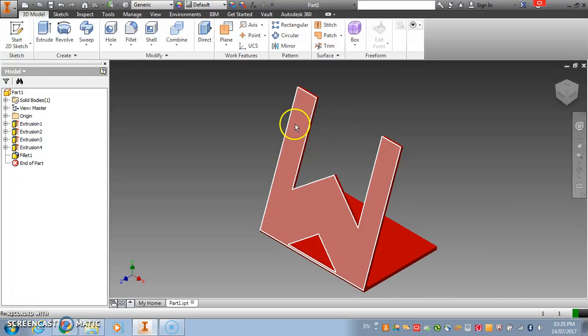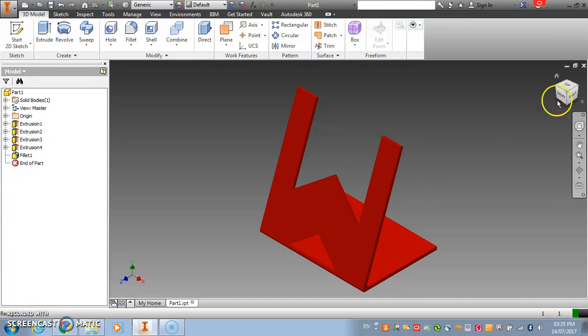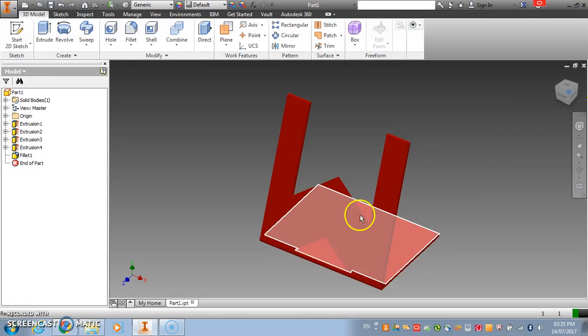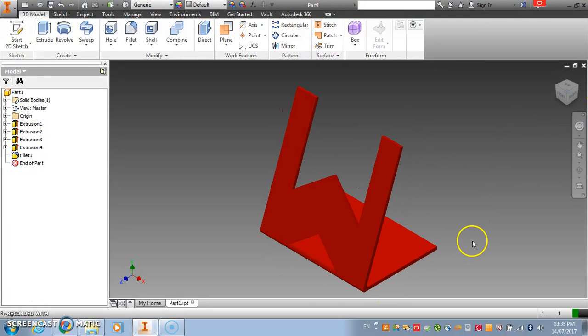A lot of people tend to like to start from this surface because it's easier to draw, but after that they find that when they try to orientate the cube, they will end up with very weird kinds of angles and they can't get a proper isometric drawing out. So to start drawing this kind of solid, whereby you bend a piece of acrylic, this is how you're going to draw it.